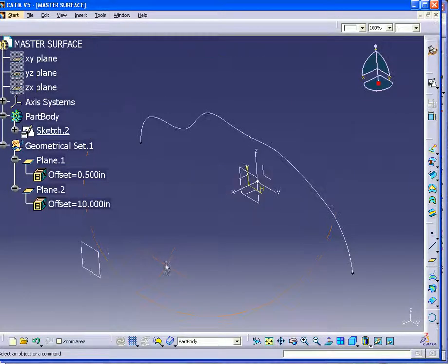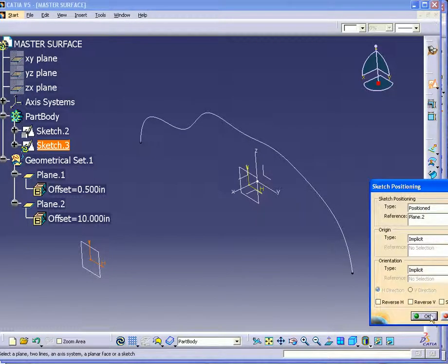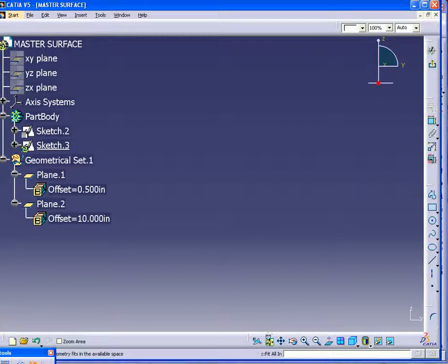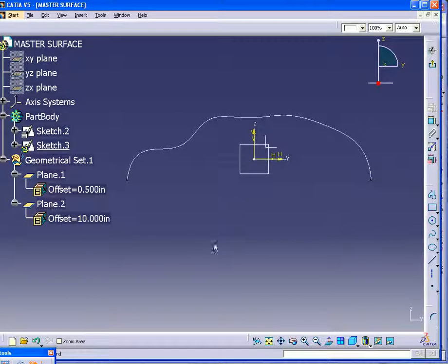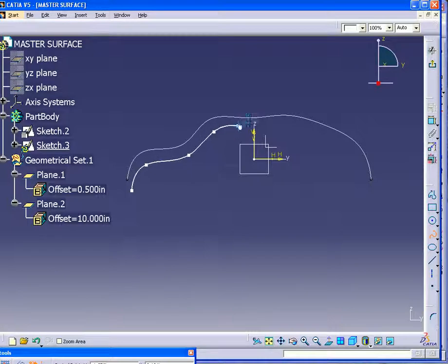So now we'll create another spline on plane 2. Again, we'll select the plane, select our sketch tool, hit OK, and we're beginning to sketch on that plane. We'll just create another spline, fairly arbitrary, just a little bit below our existing spline. We're keeping the bottom points below the XY plane of the origin axis of the part file.